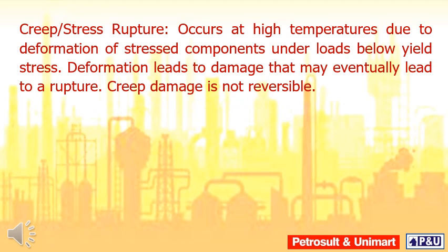Creep, stress rupture. Occurs at high temperatures due to deformation of stressed components under loads below yield stress. Deformation leads to damage that may eventually lead to a rupture. Creep damage is not reversible.